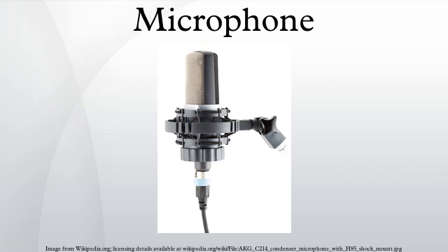If stated on its own, for example 120 decibels, it conveys significantly less information than having the self-noise and maximum SPL figures individually. Sensitivity indicates how well the microphone converts acoustic pressure to output voltage. A high-sensitivity microphone creates more voltage and so needs less amplification at the mixer or recording device.